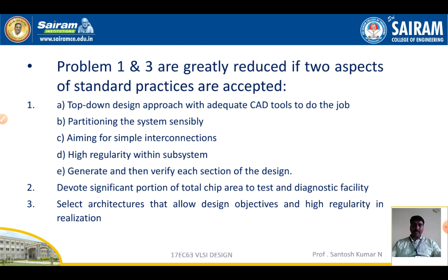This is what generate and then verify each section of the design indicates. That is, once the subsystem is designed, each subsystem has to be verified before designing a complex block using these subsystems. Devote a significant portion of total chip area to test and diagnostic facility. That is, a portion of the chip will be kept aside for testing purposes.